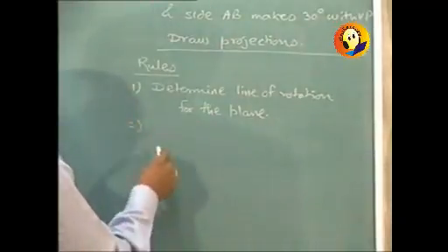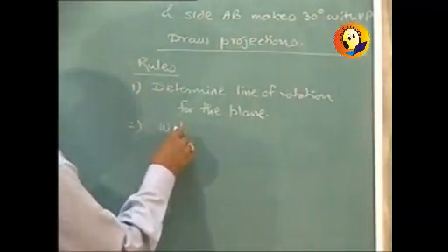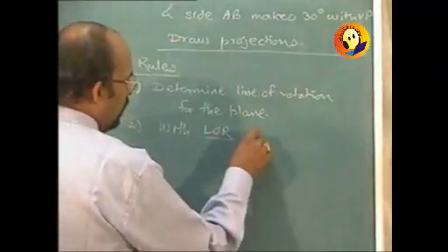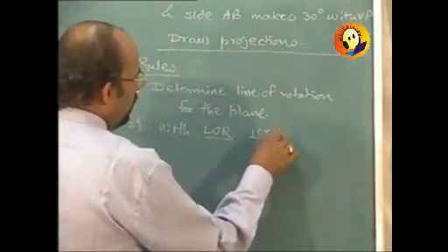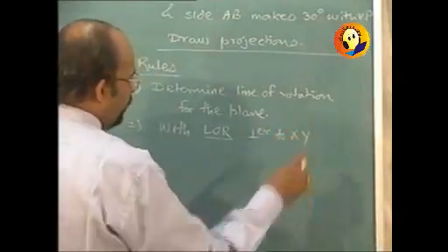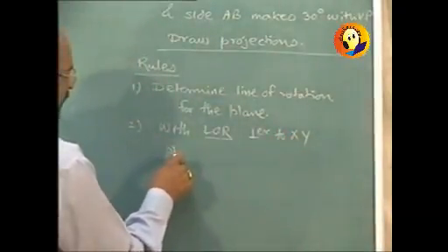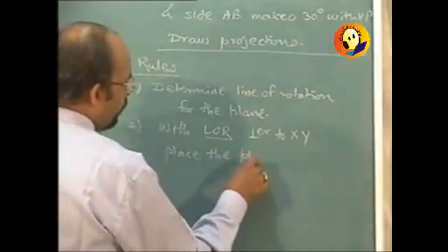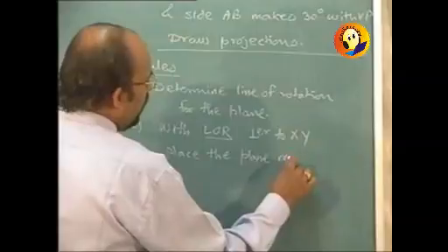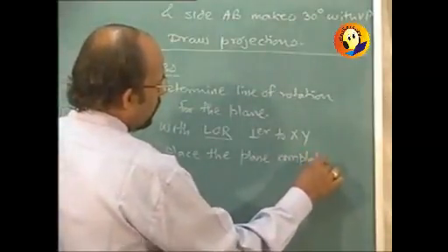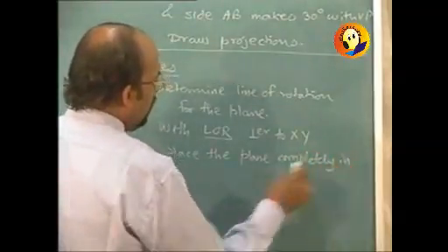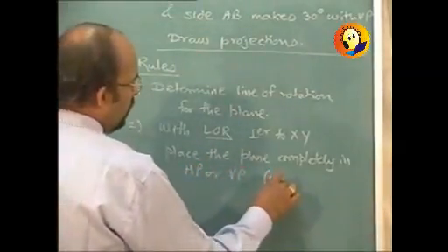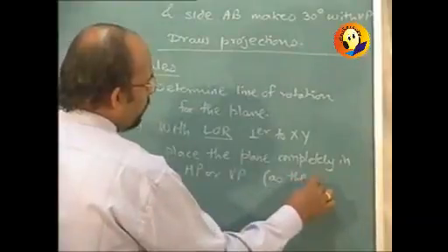Number 2, with the line of rotation perpendicular to XY, place the plane completely in HP or VP as the case may be.